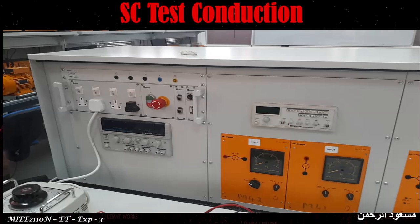In the short circuit test, what we are going to do is short circuit the secondary. Now we are going to vary the auto transformer such that in the secondary the rated full load current is circulated. In the short circuited secondary, we have to supply the rated full load current. For that, we have to first calculate what the full load current is.